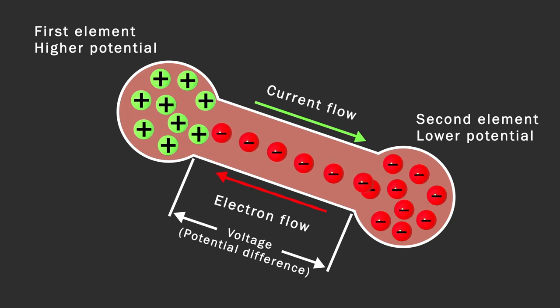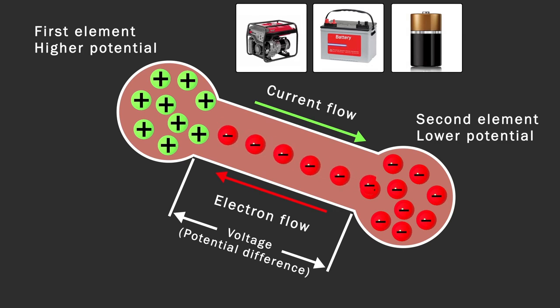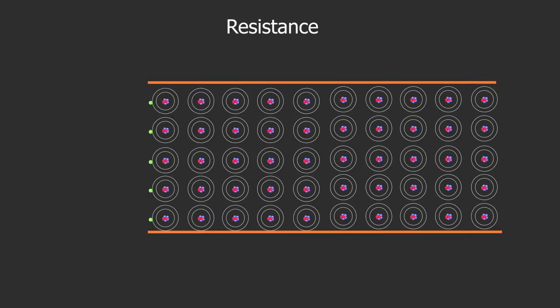Electromotive force means the force which makes current flow continuously through a conductor. This force can be generated from a power generator, battery, flashlight battery, and fuel cell, etc. Volt, which is abbreviated to V, is the unit of measurement used interchangeably for voltage, potential, and electromotive force. 1 volt means a force which makes a current of 1 amp move through a resistance of 1 ohm.